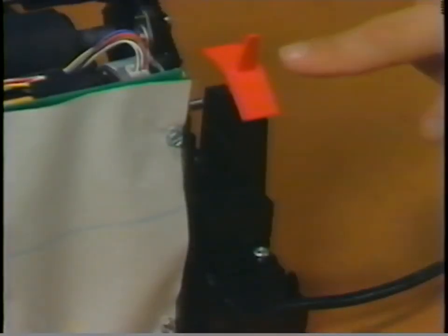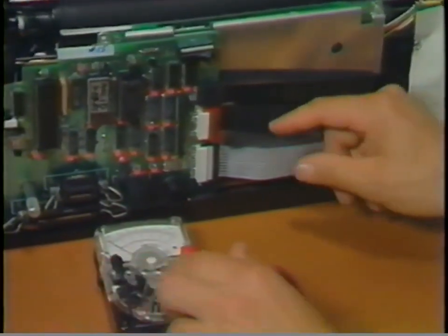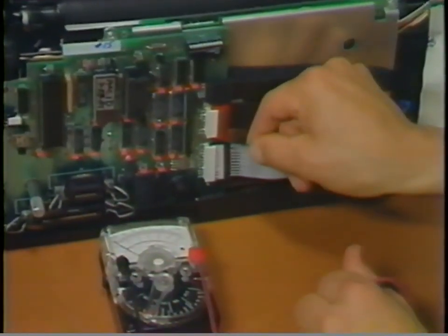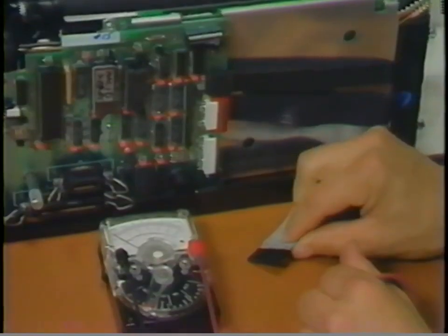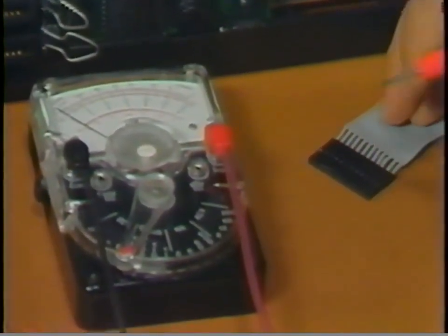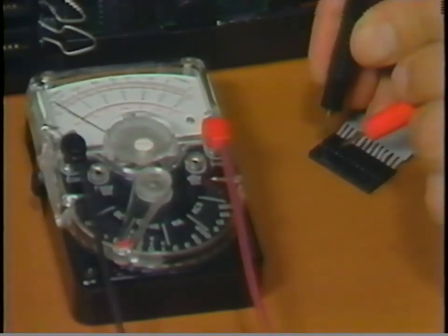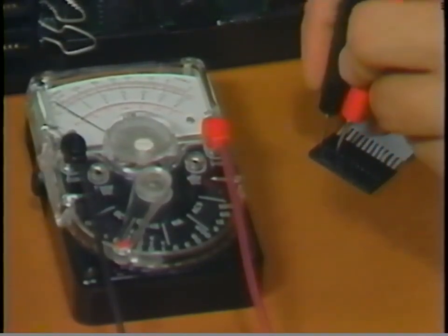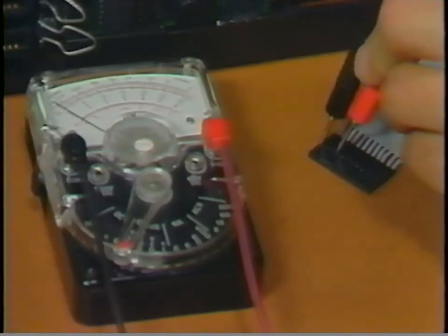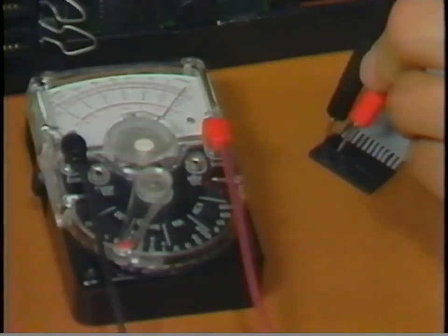The button check is used to isolate failing buttons. Turn the power switch off and disconnect J3 from the function board. With the meter on the 1 k-ohm scale, measure the resistance between ground, J3 pin 12, and the pin of the failing button. The needle should move from infinity to less than 100 ohms when the button is pressed.